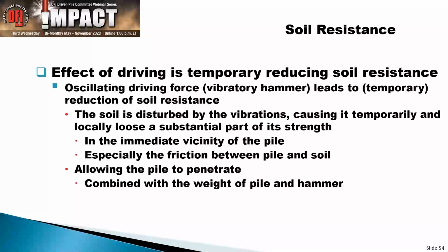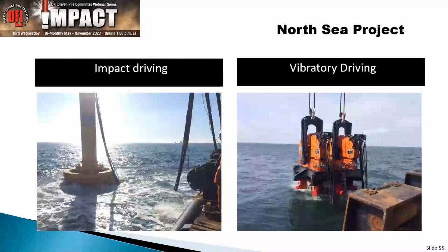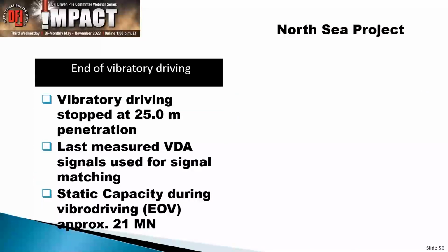Because with the larger piles, you talk about large amounts of force that allow you to get the pile to penetrate. And then, generally speaking, after termination of the driving, the soil regains most of its strength. And that's the setup. So here you see impact driving and vibratory driving side by side.